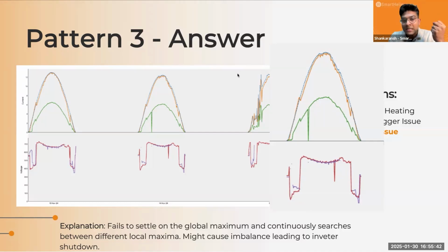But it becomes difficult to model, especially MPPTs, because a lot of different faults happen on the DC side, and MPPT is regulated. Something is lowering the current, something is lowering the voltage, and MPPT continuously tries to track and settle at a point where it can extract the maximum power. But if someone is able to track that this is happening frequently without external factors, or even after separating the external factors, this condition exists.